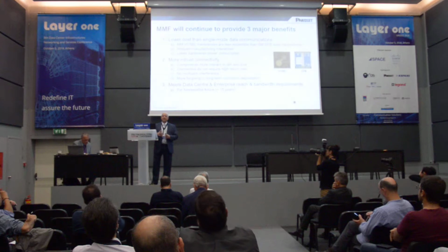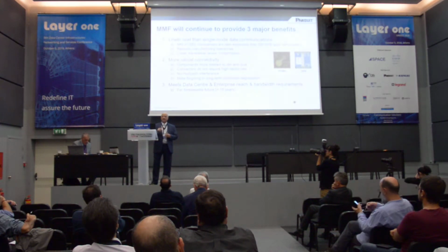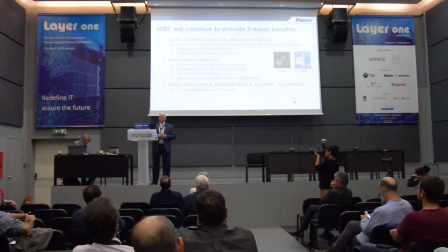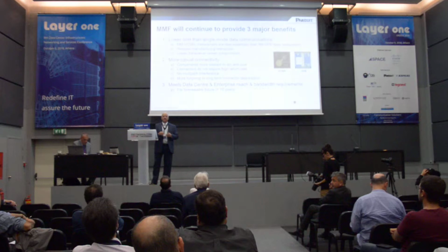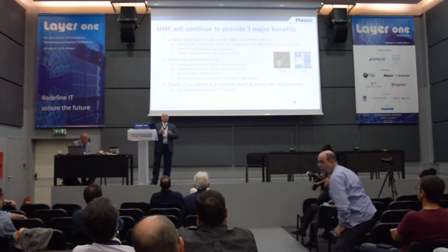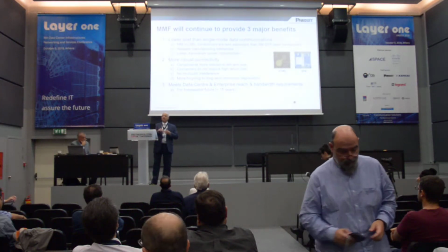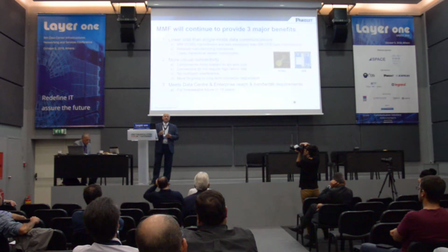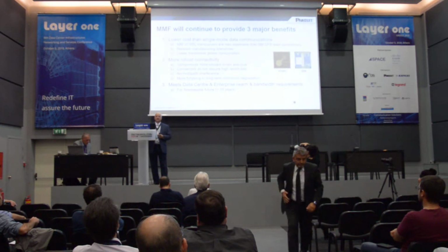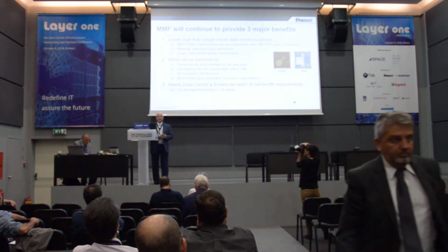They can be completely processed and tested. Bad devices are marked with ink. You can burn them in. You can do almost all the processing and testing of these devices in wafer form. At the end, you dice them. For multiple lasers, you dice them in arrays. You mount them into your transceiver, and it's a low-cost operation. Single mode transceivers are inherently more expensive.